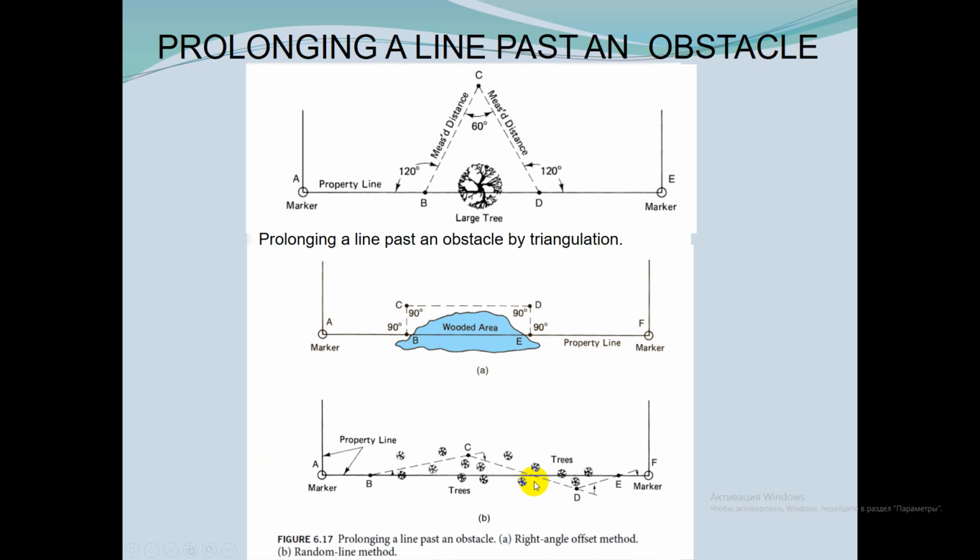The technique of right angle offsets has a larger potential for error because of the weakness associated with several short sightings at the same time. However, this technique gives a simple and direct method for establishing intermediate points on the boundary line.